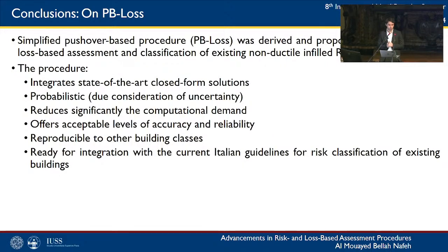To wrap things up, we propose a simplified pushover-based procedure for the risk and loss-based assessment and classification of existing non-ductile infilled RC buildings. This procedure integrates state-of-the-art closed-form solutions, is probabilistic in nature, as some of its components consider uncertainty. It reduces significantly the computational demand when compared to the FEMA P58 comprehensive approach, while still offering acceptable and significant levels of accuracy and reliability.